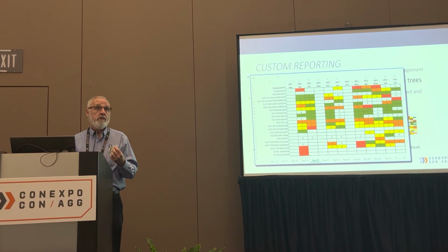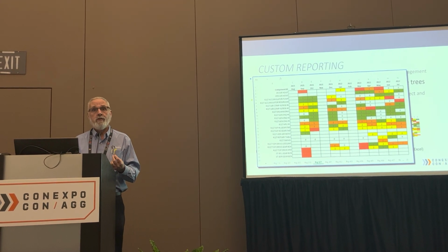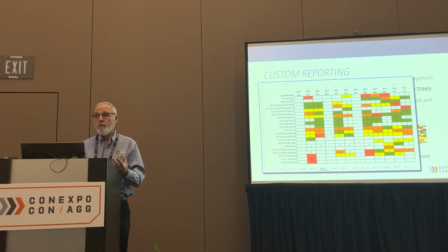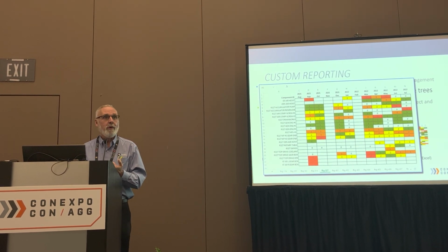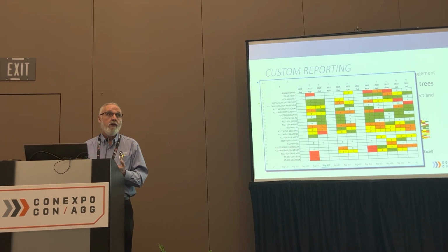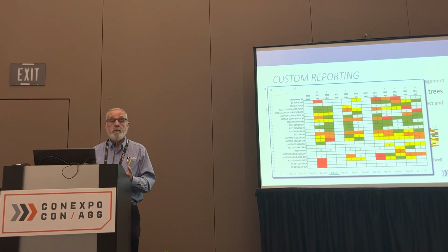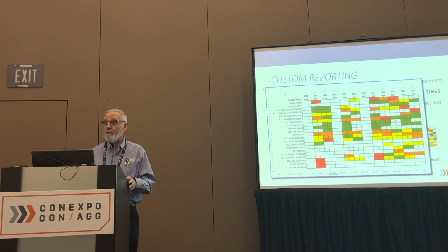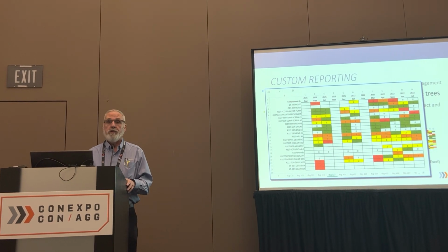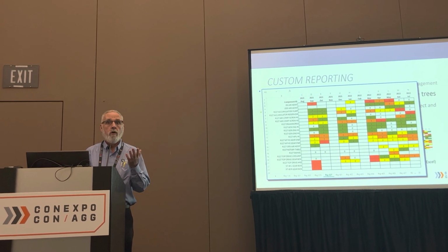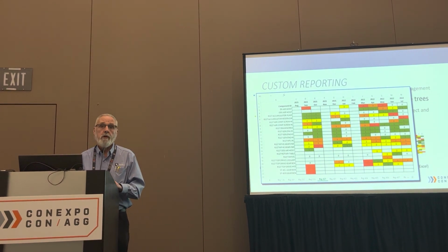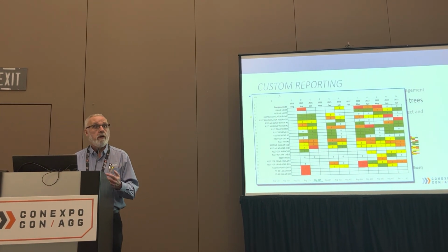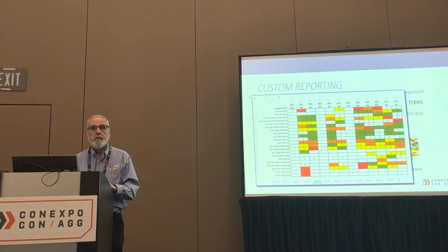But there's always that consideration: does it make sense to extend it out to 600 hours when there are other things that we need to look at at 500 hours? We knew by 500 hours we better do a frame inspection because we tended to get frame cracks at 500 hours. Couldn't risk pushing it out to 600. So there's always a check and balance, not only based on those maintenance needs, but also the production needs.